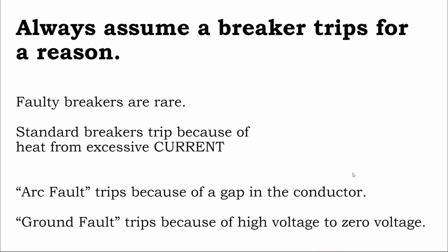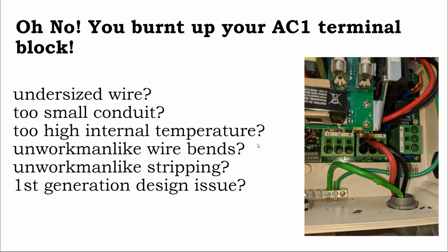A better process would be to give the system a visual inspection to see if a fault occurred because of something not going off. But in this case, the inverter didn't flag an error when just a little tiny arc connected the two together, and the breaker only tripped when you got enough current flowing. So anyway, the problem occurred without really flagging the issue.